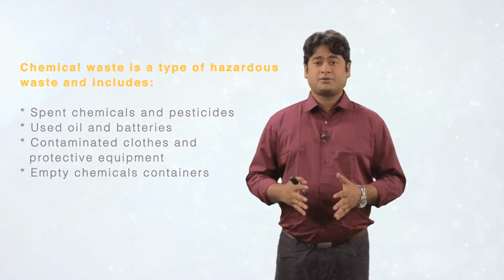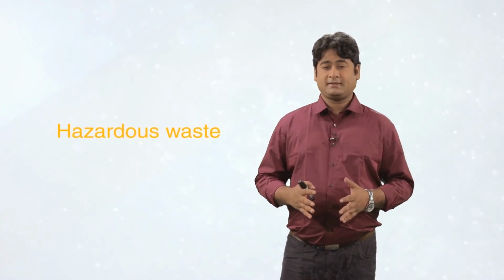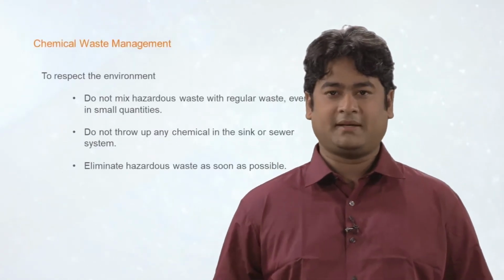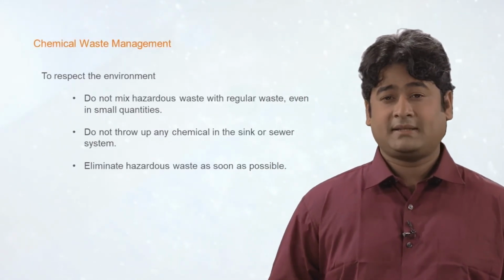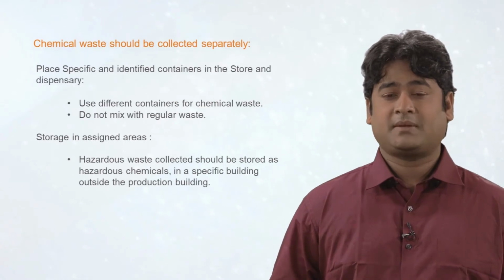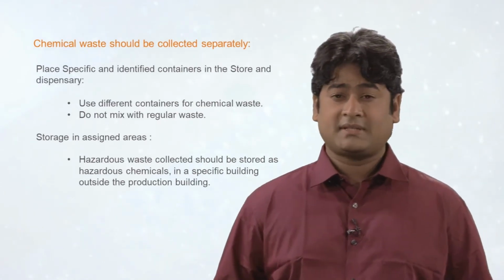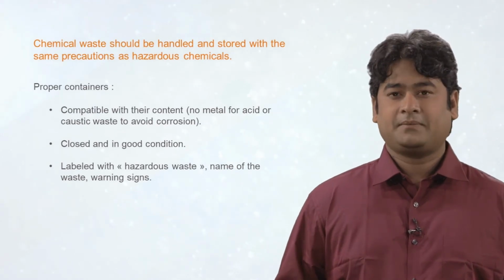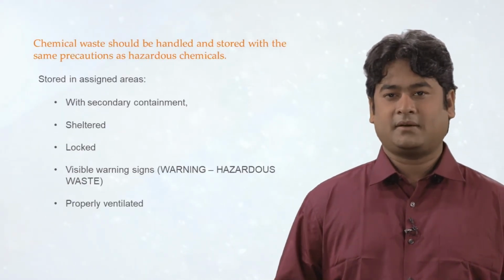There are a few precautions we need to consider while handling this hazardous waste. Hazardous waste needs to be stored in a proper container. While handling this hazardous waste, proper personal protective gear needs to be worn. This waste needs to be stored in a well ventilated area and also with a secondary containment.